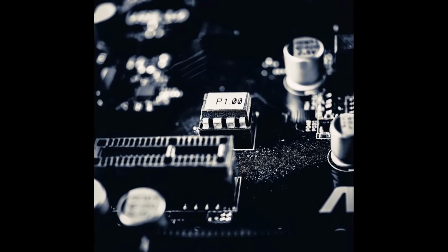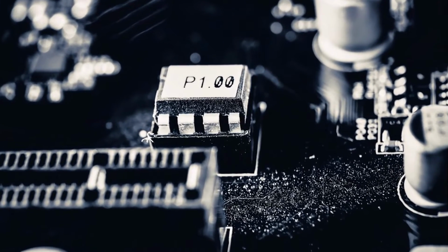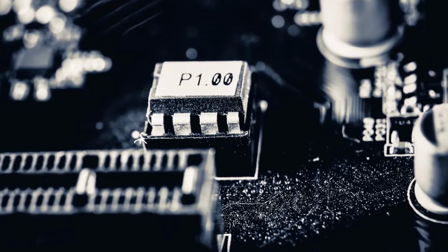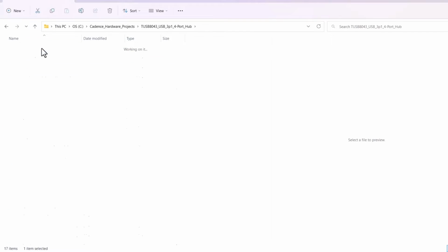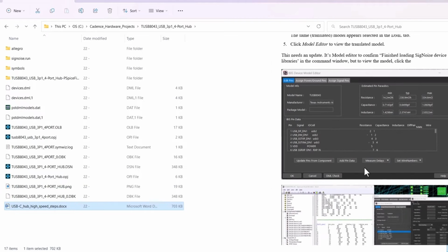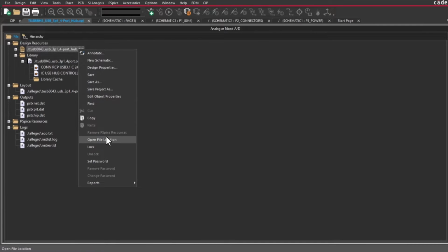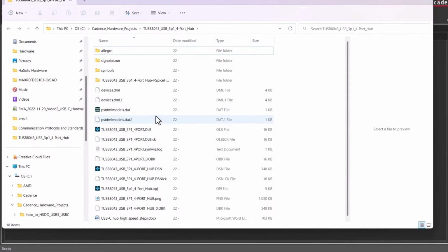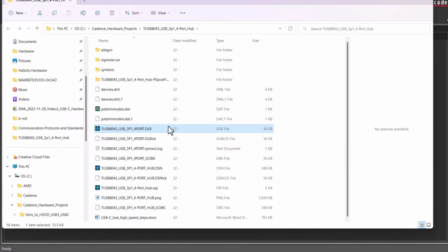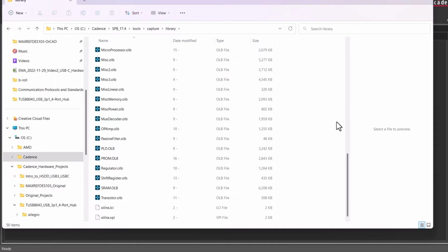You have to look at packaging, and since each part comes in various package types, like what footprints and sizes you can accommodate, whether they're going to be surface mount or through hole. You then have to organize the files and information about the parts on your computer. Then you go on to the next phase, which is the parts library maintenance in your design files, and how you would actually create the models yourself after you've selected the parts. But I don't recommend that. You want to mostly download the parts.